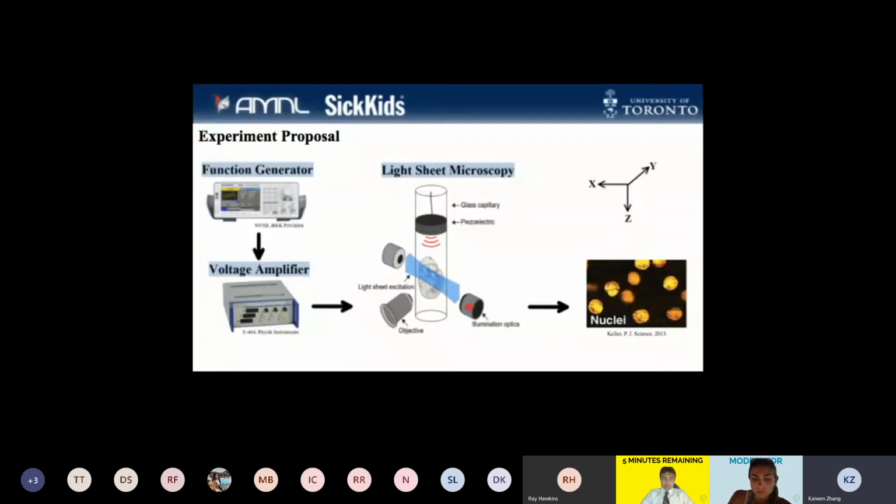We've chosen a disc piezoelectric to deliver the waves. How a piezoelectric crystal works is that when it's actuated, the thickness changes because it elongates and contracts repeatedly along that direction and generates continuous waves that travel away from the crystal. A piezoelectric can fit within the capillary because of its size and shape, and the frequency of oscillation is also adjustable depending on the experimental need. But to signal the piezoelectric, it requires a function generator that is able to output adjustable frequencies.